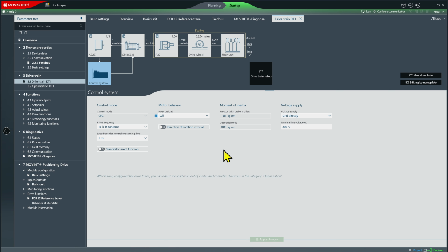Remember this, I don't actually have a gearbox or a drive wheel attached to my motor. I just have my plain old boring flywheel. So what we need to do to test it is figure out how many turns the motor is going to turn for a specific position value. Now, we know that 1 revolution of the motor produces 2.6 inches of linear motion.